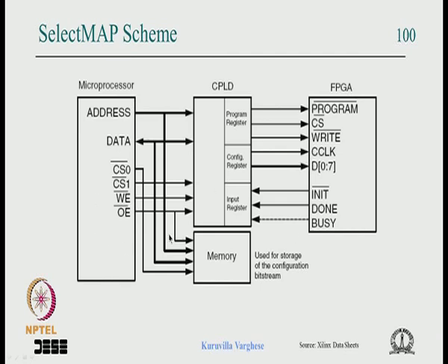So that is the scenario which is shown here, where the CPU has some memory, which could be flash, where the firmware is stored. Now the FPGA configuration bit stream can be stored here. The CPU can access that and read it, maybe byte wide: 1 byte is read here, then the byte is written there, again read and write. Such a thing can be done using this kind of scheme, and if possible the CPU can directly write if there is a synchronous port which matches the protocol.